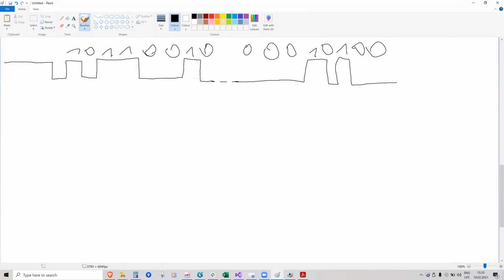So this is why after all 8 bits, there is this stop bit. So for 1 bit period, you have to hold the line high. And only when it expires do you send the start bit and the bits after that, okay?